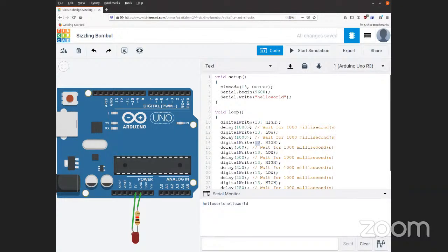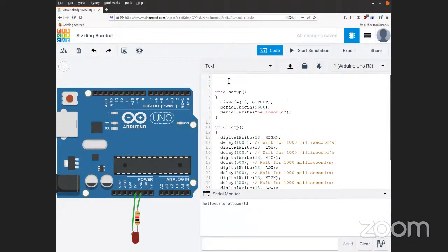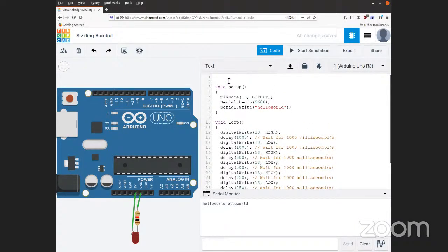So to fix this and prevent that from happening, what you would do is create a pin variable that would hold that pin number, and it gives that pin a name so you don't have to remember what it is. To create one, just declare an int type variable globally, and globally means outside of any function and at the top of your program, and give it an appropriate name.